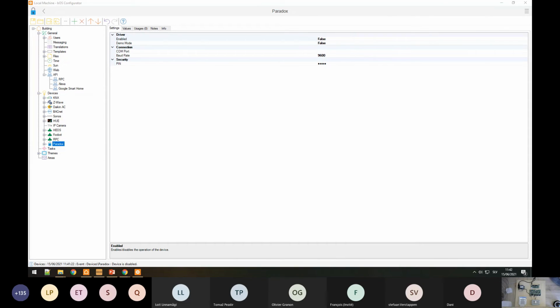So one thing you need to do before we integrate the Paradox alarm is set the zones in the alarm itself. You need to configure the zones and the unlock patterns on the keypad itself. The device, of course, comes with an instructional manual showing you how to set the passwords, set the zones, and everything. We have already configured the zones for this. Each individual zone here is connected to the alarm, and triggers the alarm if the alarm is, of course, in the ARM mode.